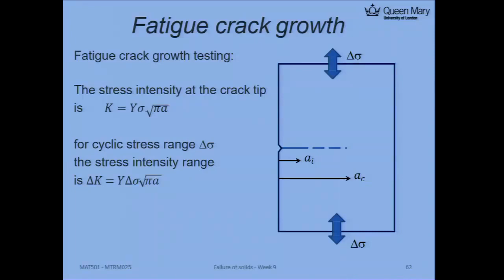And the total change of your stress intensity also will become a range. Suppose you have a material, you need to think about how far you stretch the material from the minimum to the maximum. If you reduce the range, you also reduce the fatigue failure. So that's why we always have a delta here. Delta K is now equal to delta sigma times the square root of pi a. The crack length definition doesn't change. Only these two change, K and sigma.